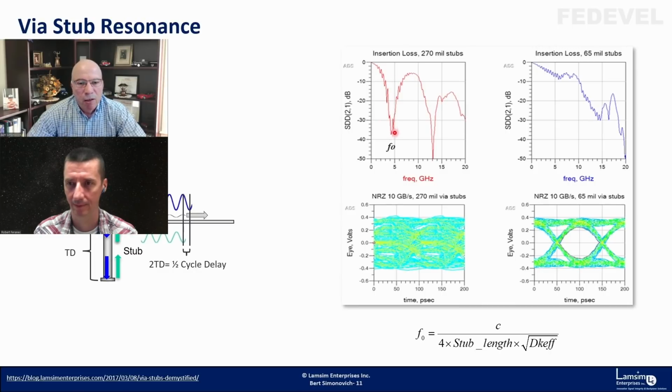What the silicon can't do is something like this, right? We have the resonances. So, for a backplane channel, a lot of the specs talk about roughly 30 dB from chip to chip, on one board to the other through a backplane. Depending on your material and a lot of factors, that can be different lengths.